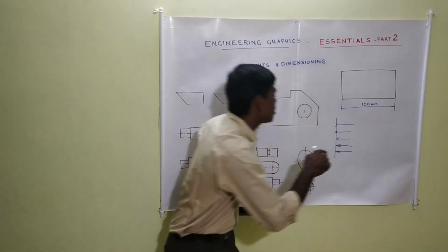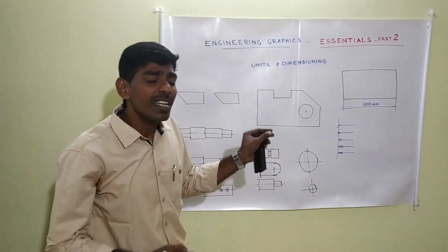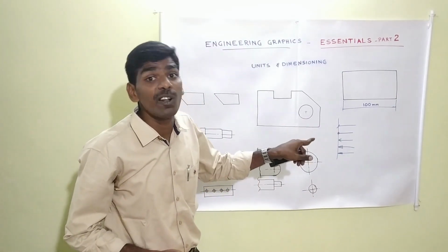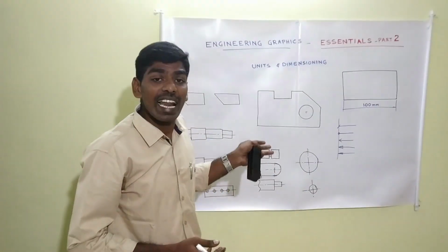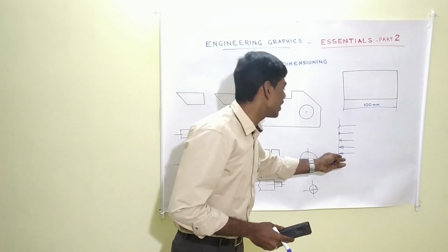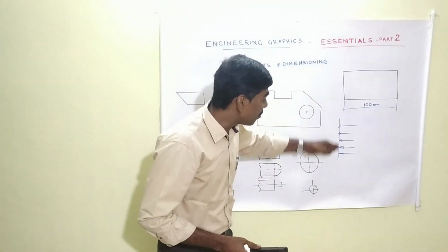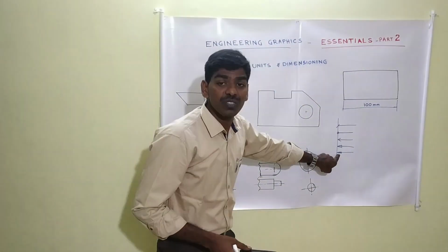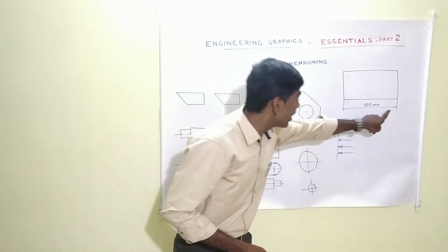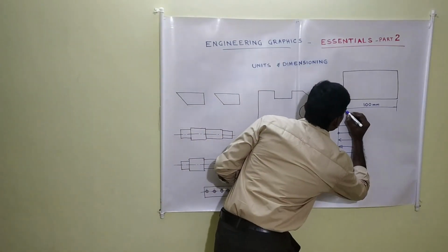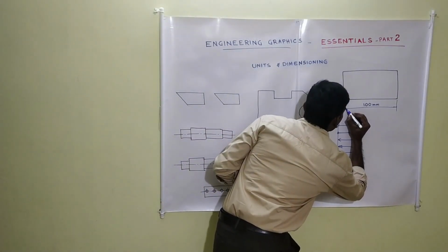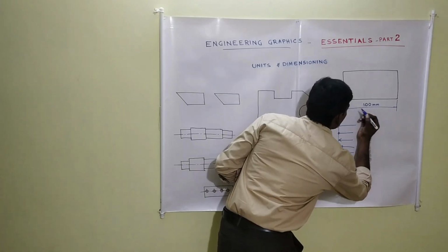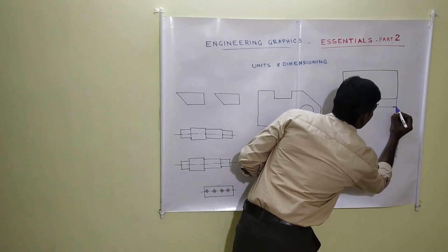Here it's a closed filled arrowhead. These are some of the types of terminations that are being used. We can select any one of these. I would like to go by this one. So here, terminations. I can opt for this one. So from here to there, I can make it this way. I can make an arrowhead. It is closed and it is filled.